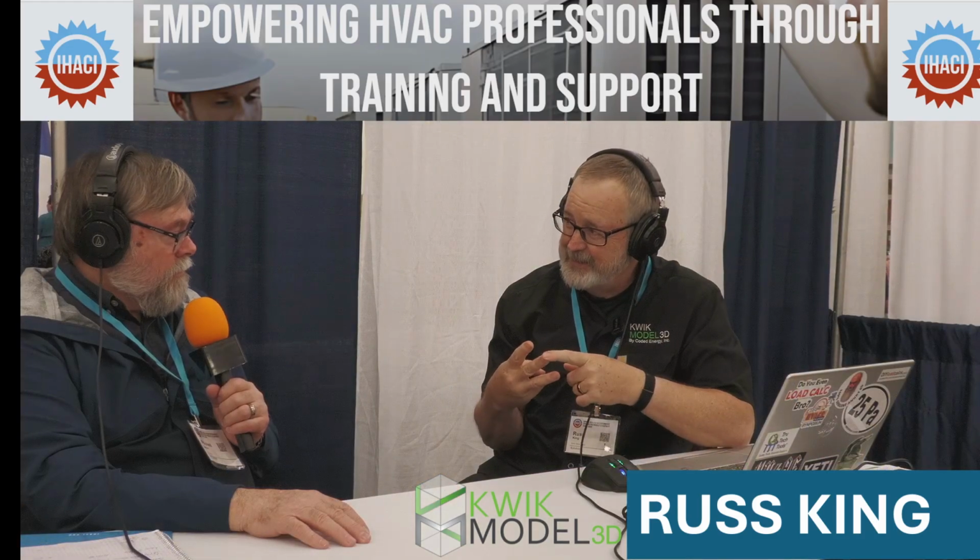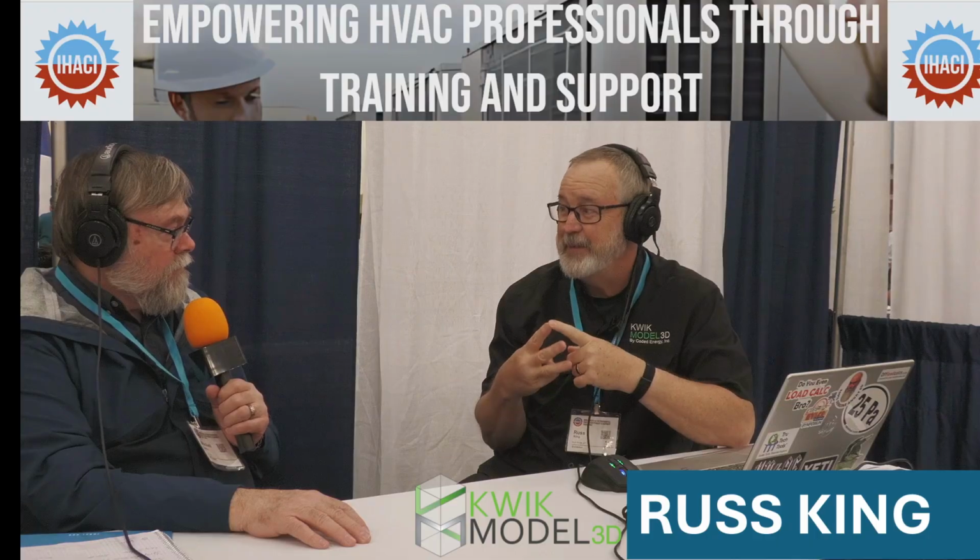Okay. So I don't know if you guys know, and Russ can explain that to you, but next year you're going to have to do a load calculation when you do your Title 24s. Manual J, S, and D is the only thing I know of that's actually required in 3 different codes. It's in the mechanical code, it's in the energy code, and it's in the green code. And it's been there for a long, long time. The problem is that building departments just aren't asking for it.